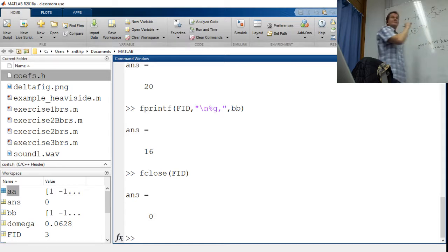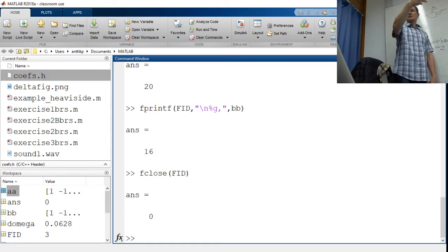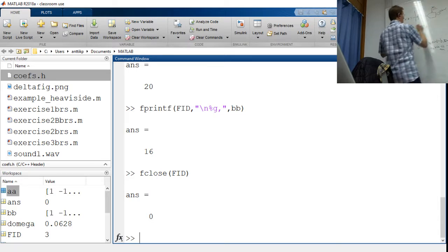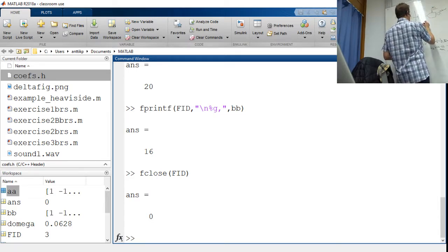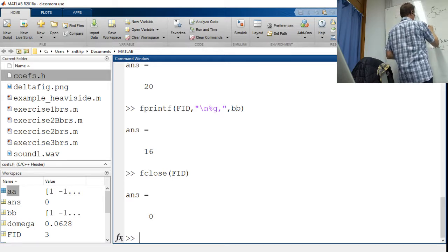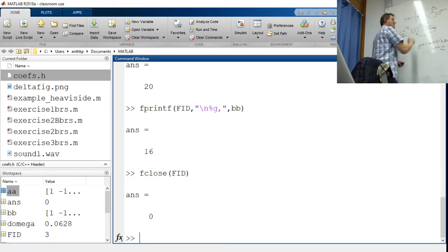I would do block filtering. So you have a counter here, counter++, which counts how many samples you have already got. And then when the counter is equal to some big number, you go and do the filtering in a block. Return to idle. Okay, so otherwise what happens?